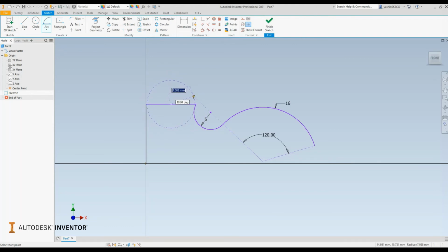So what it's going to ask me to do is select the start position, and in this case I'm going to choose the end point of the line and go all the way across to the other end, and that will be my center point arc. Okay, so it allows you to define the angle as well as how far it's going to rotate, which will essentially define the entire length of the arc.